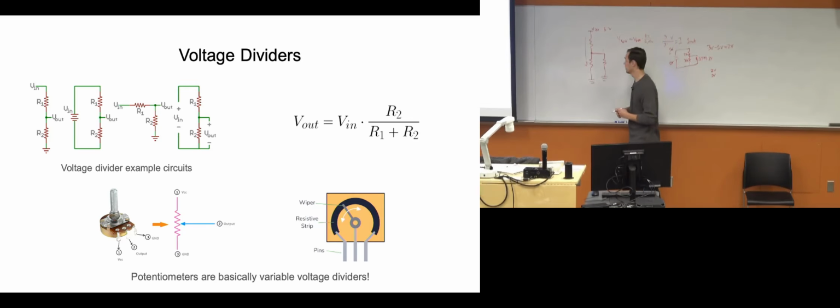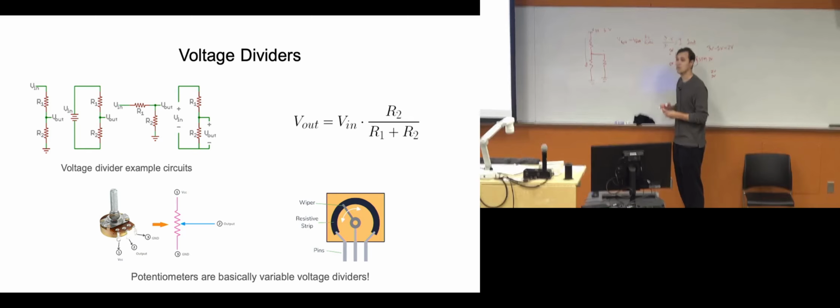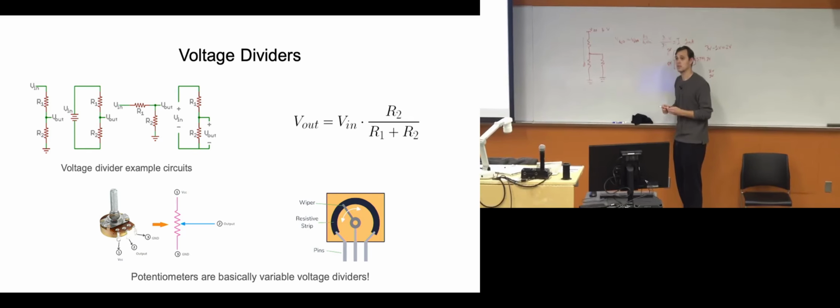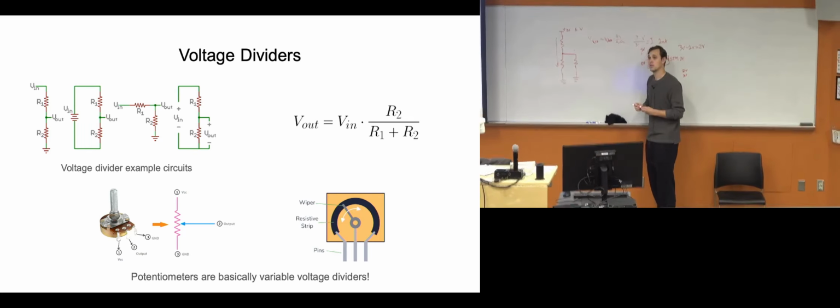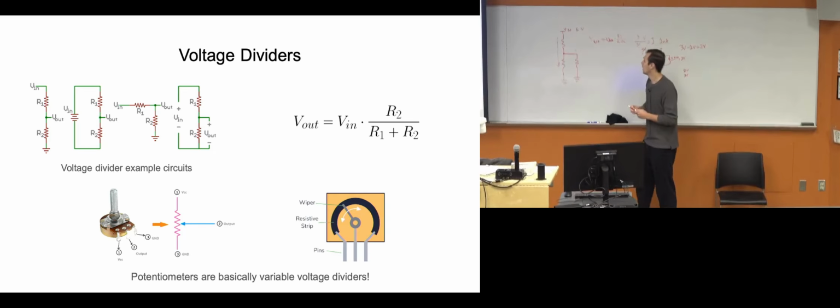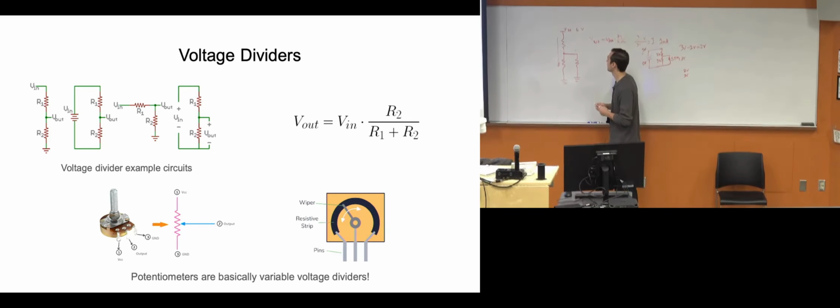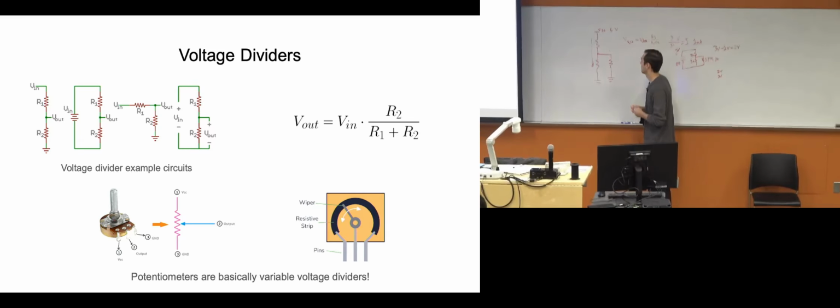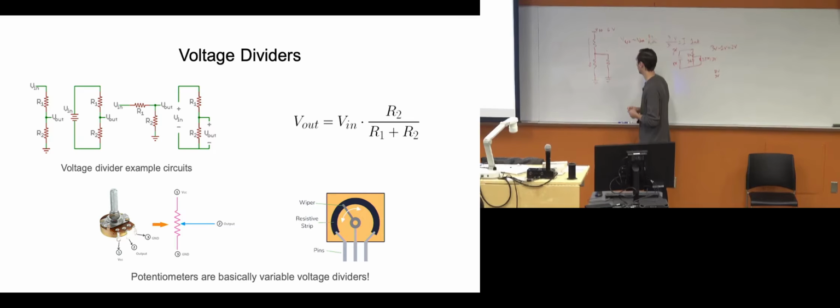Yes. So if we're using that as a voltage divider, like we take the V out pin and then we connect it to a resistor, wouldn't it mess with the actual input voltage we end up getting from the voltage divider? Yes, it would. That's why most of the time, when you do this, you would put a buffer here. You guys also haven't learned about this.